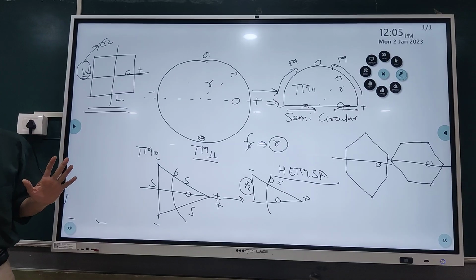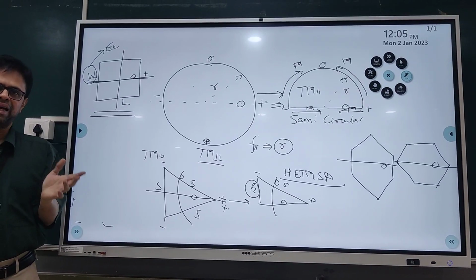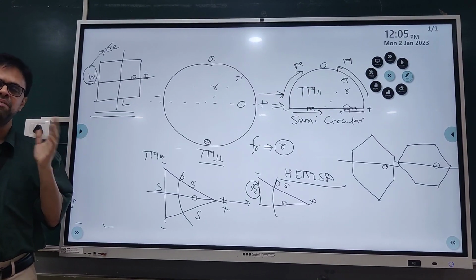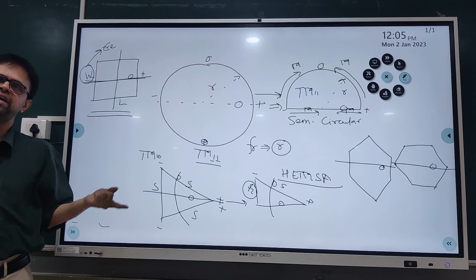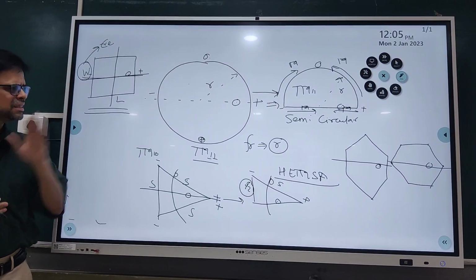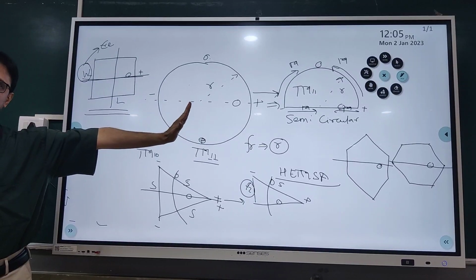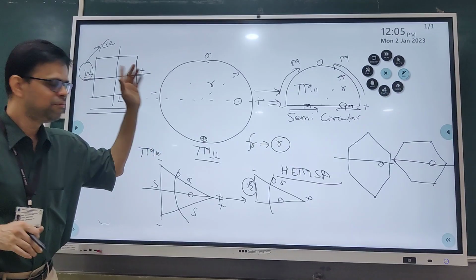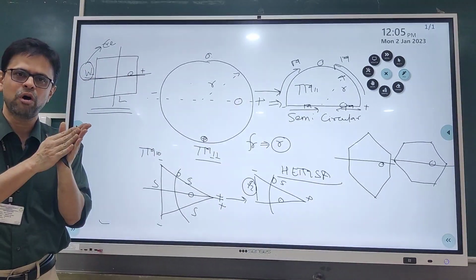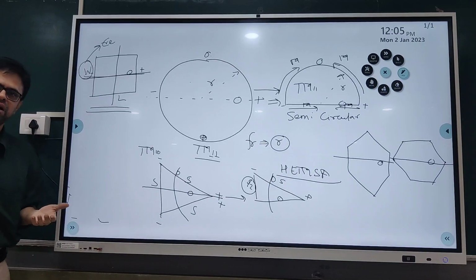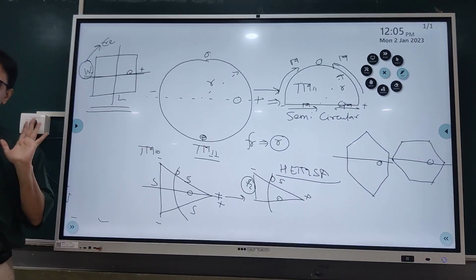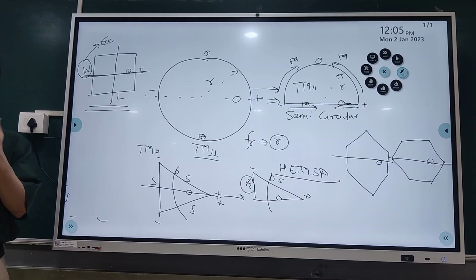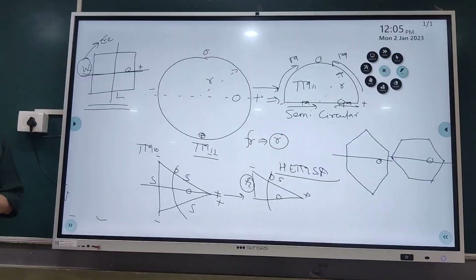For this, you need to understand how the magnetic dipole models are evolved, which we have covered in the basics of microstrip antenna, where we drew the magnetic dipole model for the rectangular patch. Using that, you can see why we defined a radiating edge and a non-radiating edge. With respect to the basic rectangular patch, the same explanation is applicable to the circular patch as well as the equilateral triangular patch. Just to put on record, we discussed that time that the RMSA offers better performance in terms of cross polar level, whereas the ETMSA has a higher cross polar. The same explanation can be seen by considering the magnetic dipole model and the fringing field distribution, which we have covered earlier.